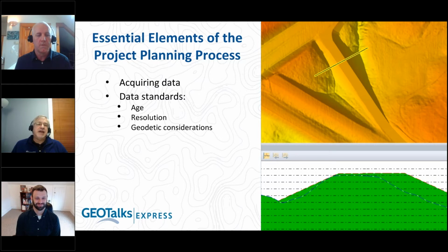And when taking the NAD 83 2011 data from the one state and just treating it as the original realization of NAD 83, they did align. So there seemed to be a metadata problem there. I don't know how that was ultimately resolved, but it was just a conversation I had with an engineer that ran into that problem. So making sure the metadata is actually correct is very important.